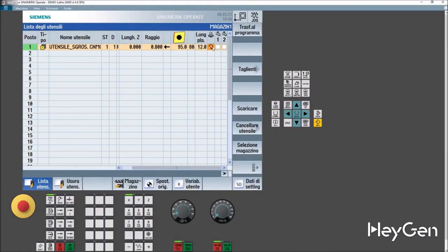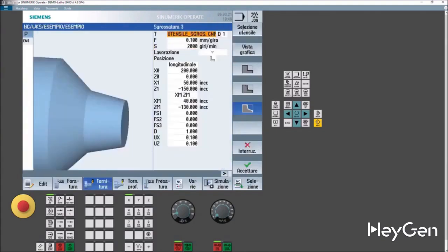The rotation sense of the tool, and whether you want to use water or even high pressure. It transfers to the program, and here it inserts the roughing tool with an F and an S, let's say standardized. Then you can go on the F table and write 0.3, like millimeters per revolution for roughing at 2000 RPM or meters per minute.